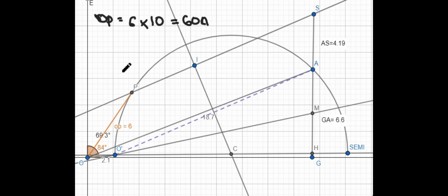As already given in the question, it is a delta connected network, so converting this phase current into line current, we multiply by root 3. That is root 3 into 60, which comes out to be 104 ampere.